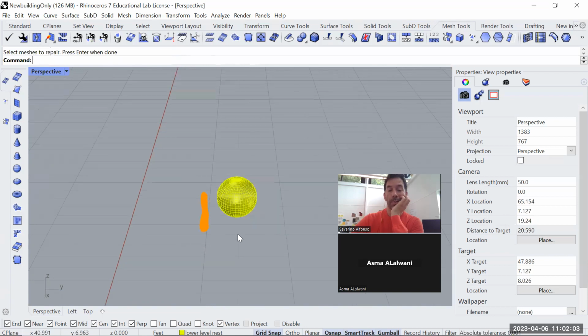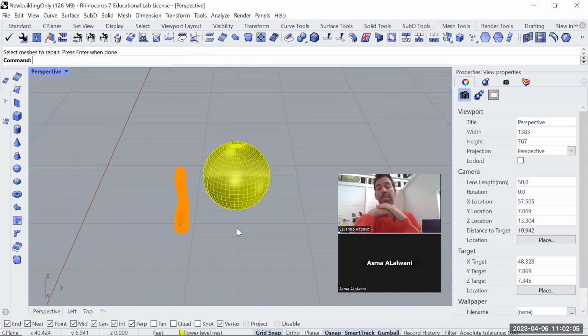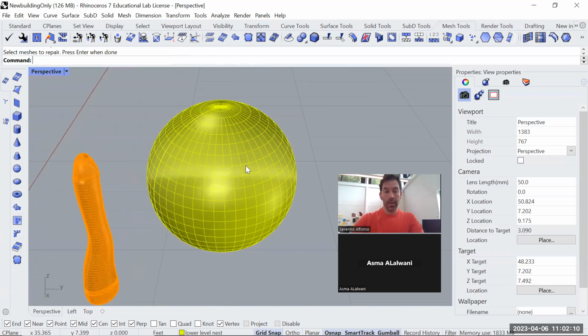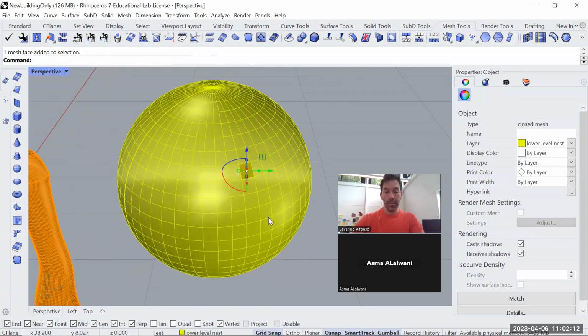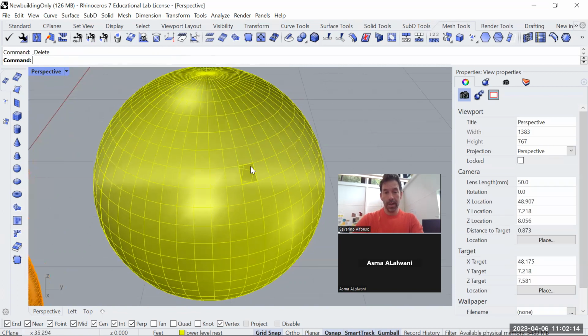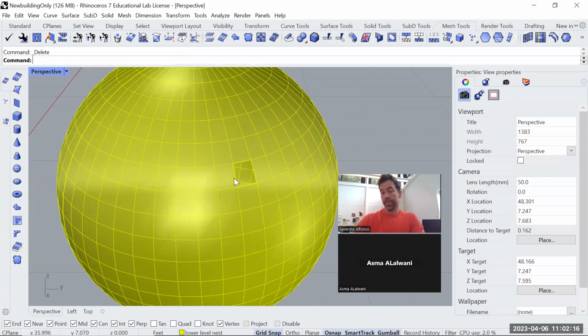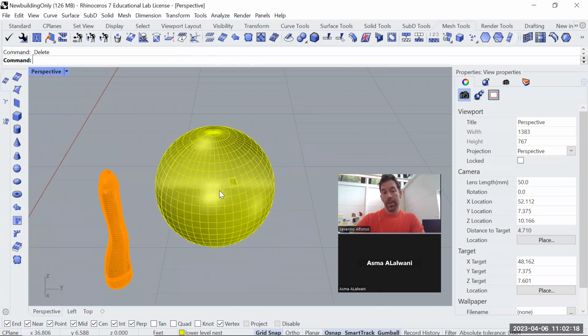Okay. What problems could you have as a mesh? Why wouldn't you be able to 3D print? Well, it has a hole in it. So it has to be watertight, is the famous term. If I delete this face, in theory that would be a problem. Now, I think the machines are getting smarter and smarter, and this type of opening is not problematic. But I would try to avoid having those problems.